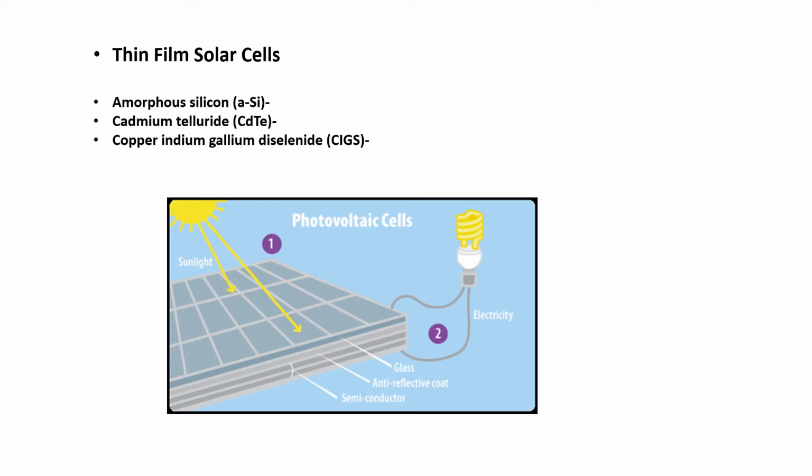The main feature of thin film technology is to look for properties and better efficiencies at lesser material bulk, whereas silicon wafer-based solar cells work with wafers of typically 350 micron thickness. The thin film technology is working at 1 micron thickness, which is 1 millionth of a meter.